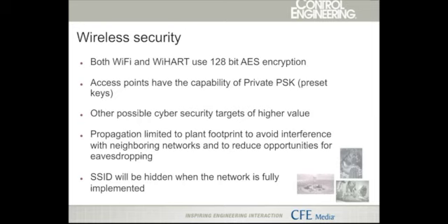We also used transmitter power control. We limited the propagation to the plant footprint to avoid interference with neighboring networks. You don't want to get complaints from the neighbors that we're stepping all over their network, and also that will reduce opportunities for anybody who's eavesdropping.